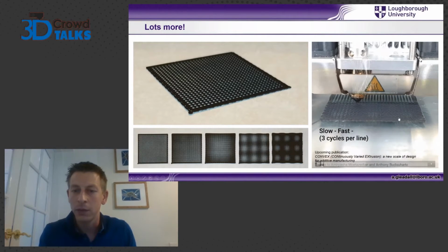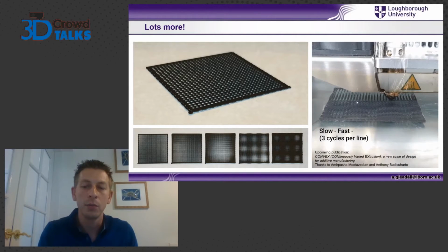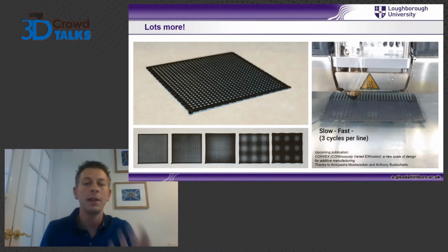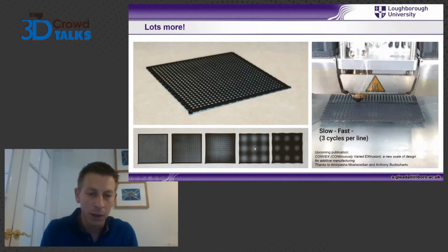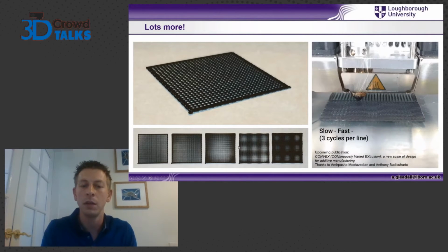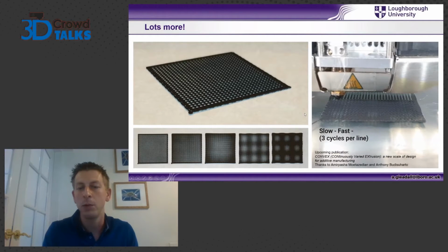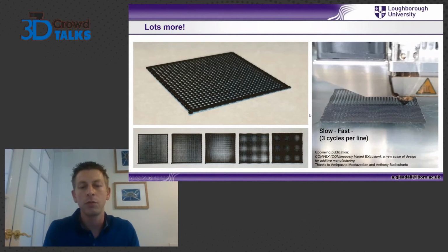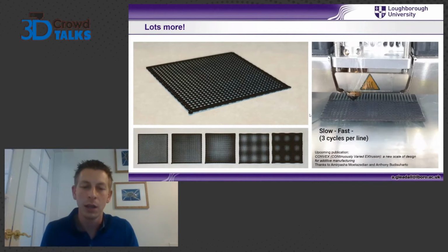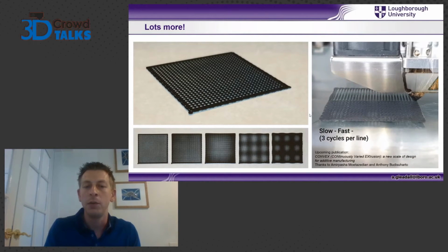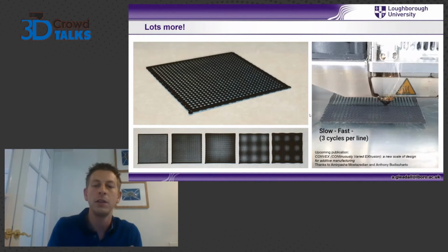So on the right, you can see how we're going fast, slow, according to a sinusoidal function, and that ends up with us having more deposition, less deposition, so we can get a really controlled design structure, which is what those two images at the bottom middle of the screen with more porous sections are achieved using. So through custom G-code, it's offering completely new design opportunities that just aren't possible if you were just going to use a slicing software, which would not be able to constantly vary the filament.